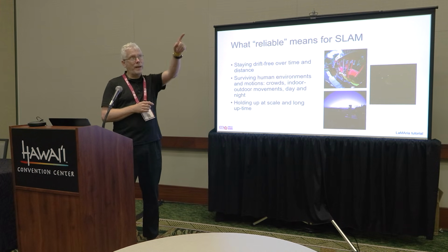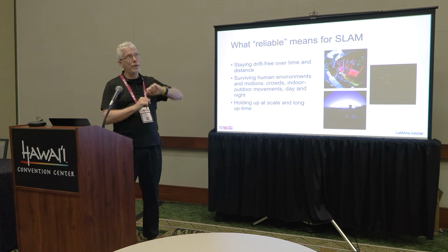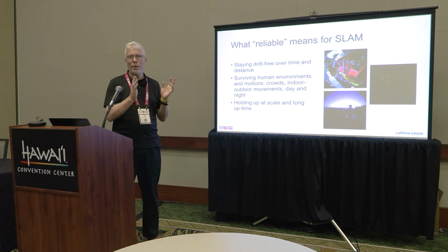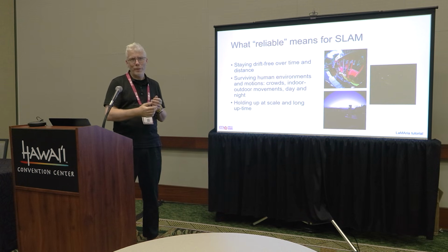However, if I identify a few reference features, landmarks to track, then I can stand still for an hour, and as long as I still see the same features, I will have no drift. I will know that I'm still exactly in the same position watching the same thing. That's something with inertial sensors, they essentially drift. In particular, the orientation drifts slowly, but the position drifts very fast because you have a double integration. And double integration of the noise means you very quickly drift off.